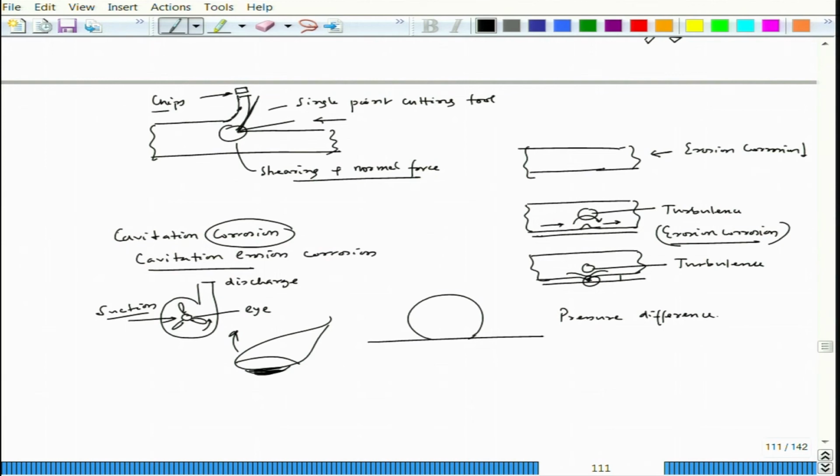If the pressure goes low, so that the pressure exerted in that particular water system is less than the saturated vapor pressure at the temperature of that fluid, then water can evaporate, and that evaporation leads to a small bubble on top of a metal surface. Okay. So, this is the bubble, let us say, and in that particular fluid process, at some location